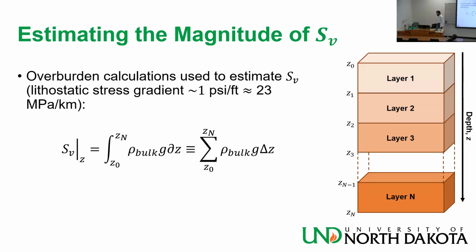The weight, as in pound mass, can very easily become force, pound force, and then the area it's acting on, square inches, pound per square inch is PSI. So for every foot of depth, you have a certain amount of PSI.